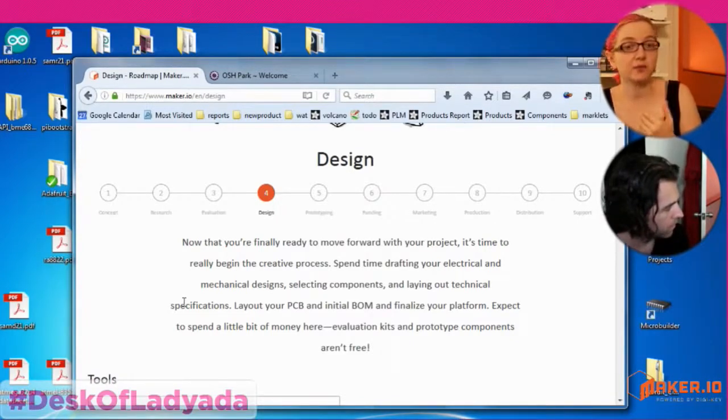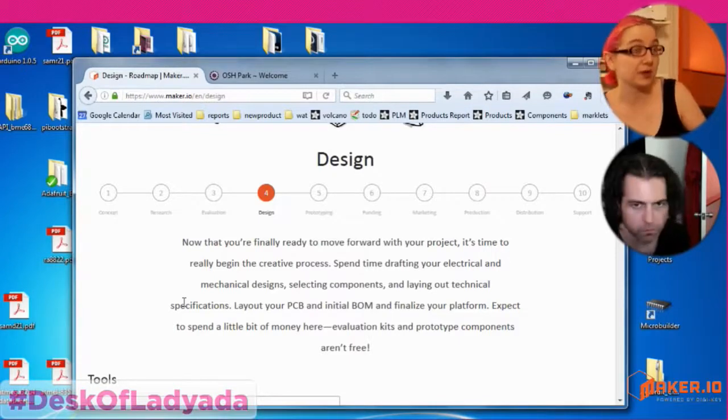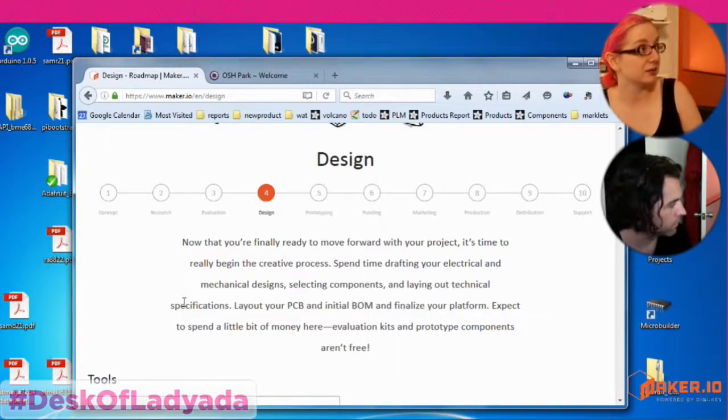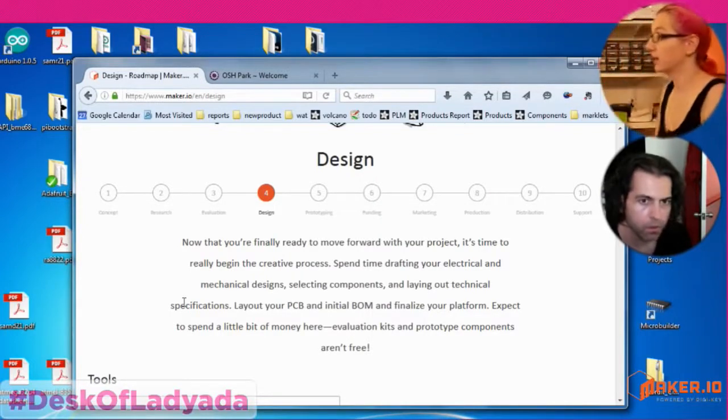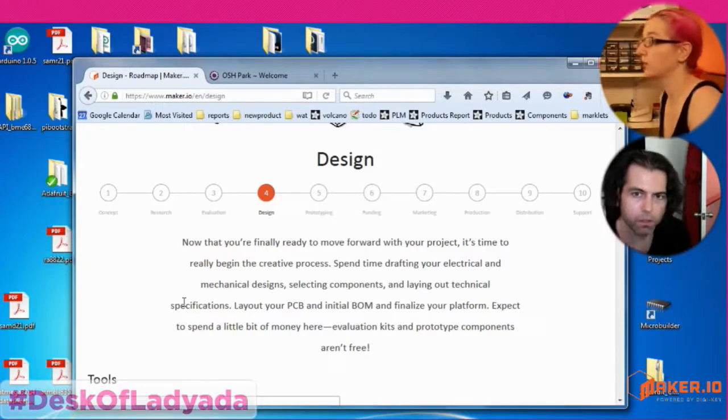Check the lead times. And pick your parts because once you lay out the board and then you take it through certification, it's very hard. It can be hard to go back and reroute the board, and then you'll have to redo your certifications. Maybe not so bad, but it's something to keep in mind. It can add up a lot in scrap costs or so, now that we're reworking.